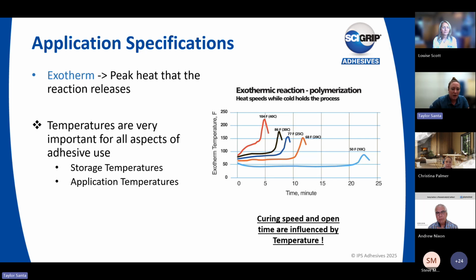You need to consider manufacturers' recommended gap and bead size when really researching adhesive. Some adhesives are designed to have lower exotherm temperatures in large mass, making them perfect for gap filling. So, for example, our SCIGRIP's SG230 high viscosity series is created to not boil when applied in large bead sizes up to 2 inches. If you need to fill a gap this size and tried an adhesive not designed for gap filling, you'll see a lot of boiling and bubbles in the large mass of adhesive.